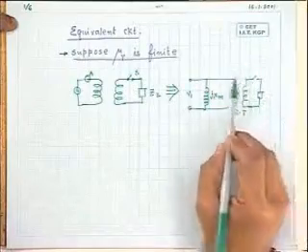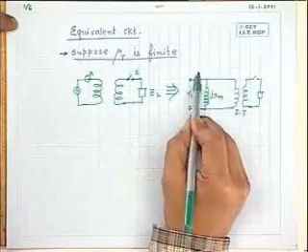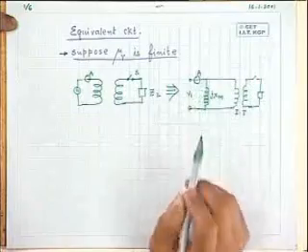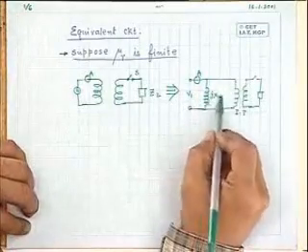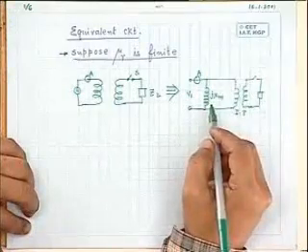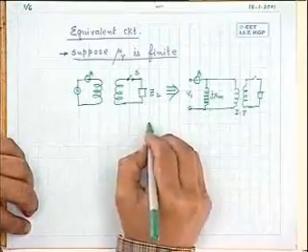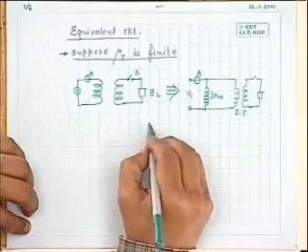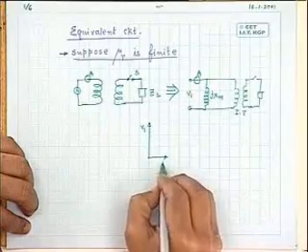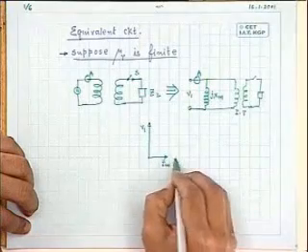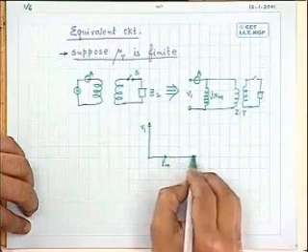For example, when the switch is open, the ammeter will read V1 by Xm. Why it is represented by a reactance is quite obvious, because the magnetizing current will lag the supply voltage by 90 degrees, the direction in which the flux is developed.